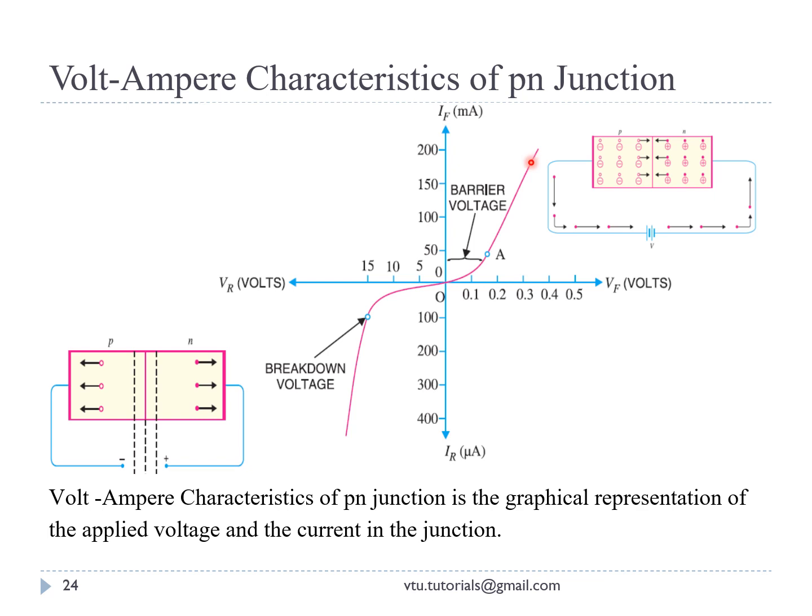And now going into the reverse bias condition. When the junction is reverse biased, that is, P-type connected to the negative terminal and N-type connected to the positive terminal, the potential barrier increases, as we have already studied. Therefore the junction resistance becomes very high and practically no current flows through the circuit. However, a very small current due to the minority charge carriers flows through the junction, and this is depicted